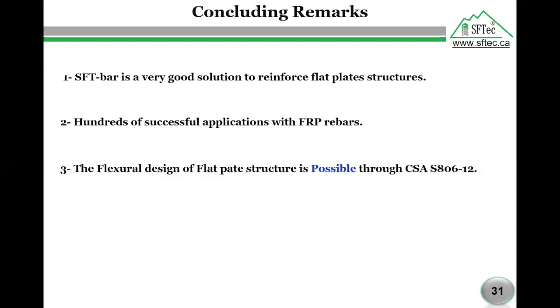The flexural design of flat plates is possible through the Canadian standard S806, using the plane section analysis as in the Canadian standard A23.3, but with adaptation to include the tensile properties of FRP bars instead of steel. Due to the lower modulus of elasticity, deflection and crack widths will govern the design.